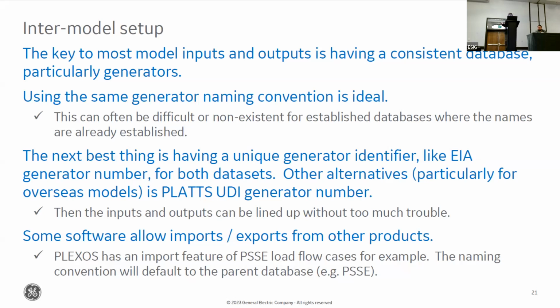I will say that some software has import-export features. So Plexos does allow you to import PSSE power flows, but there's still a lot of work that has to be done once you import that to incorporate the line limits and contingencies and so on. And unfortunately, when you import it into Plexos, it just adopts all the names that are in PSSE, and PSSE basically uses generator bus numbers for each of the generators. So PSSE is a bit tricky sometimes.